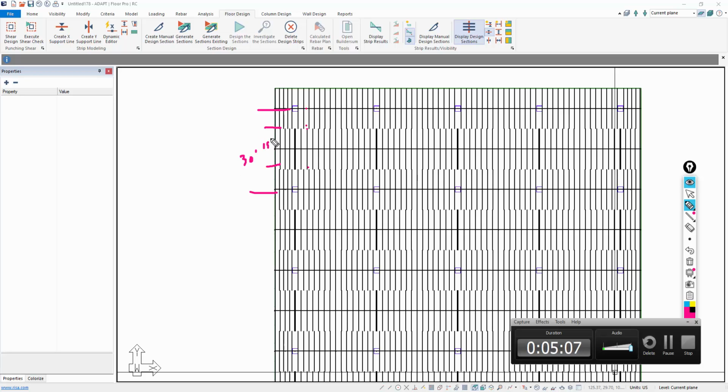It's 15 feet. This is 7.5 feet and 7.5 feet. That's the automatic breakup of how the program would categorize the column strips and the middle strips. The middle strip is always going to be 1/2 the distance of this bay automatically, unless we somehow modify the percent allocation of the column strip.